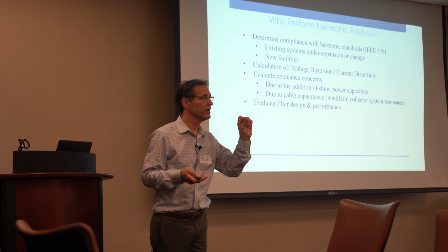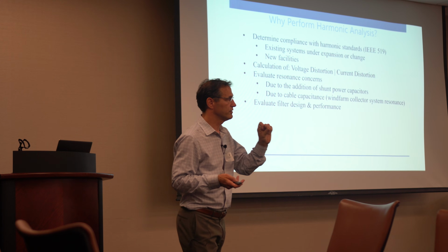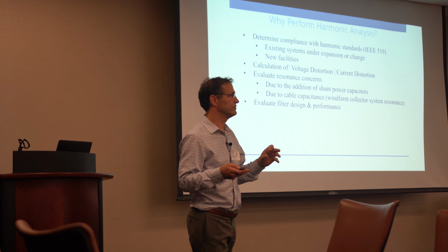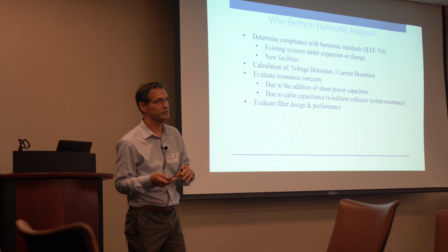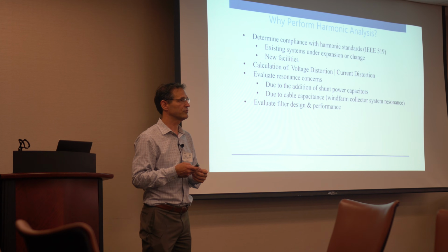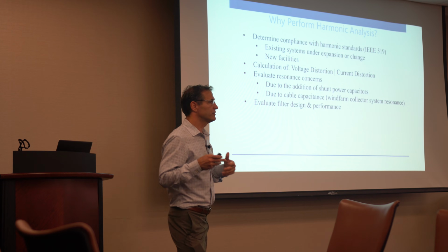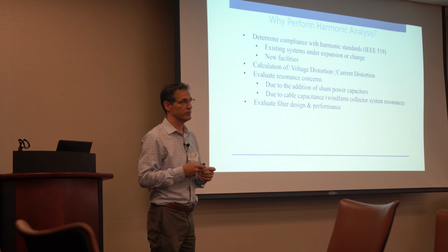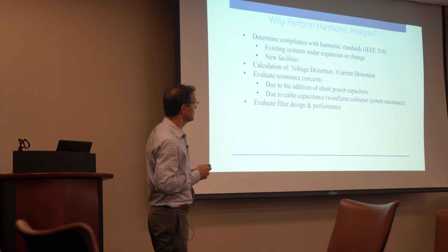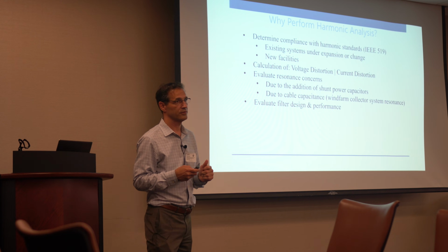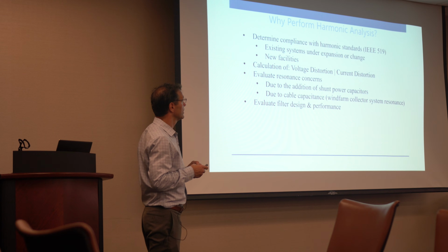Maybe a small amount of additional heating, but I could tell you the additional heating is very minimal. Okay, you have transformer issues kind of down in the lower voltage network that you have K-factor transformers and things like that. Yes, you're concerned about that. But once it's into the network, harmonics is not really a major concern on those devices from a current standpoint. But voltage is a power quality concern, and that's something that you're looking to calculate when you do analysis.